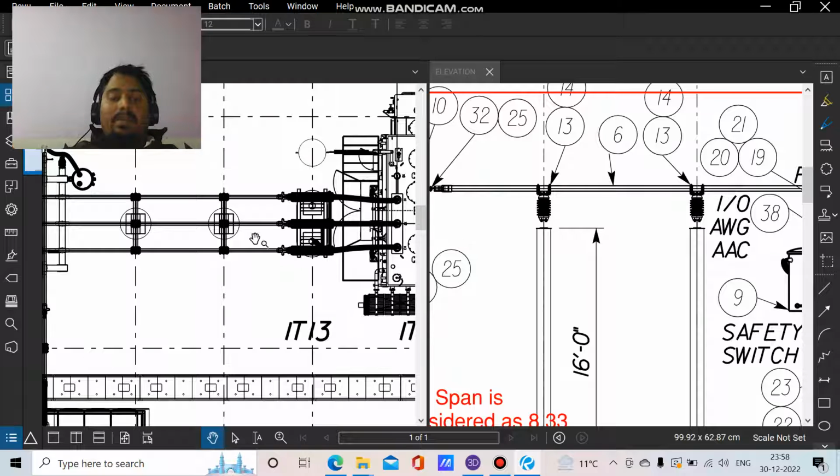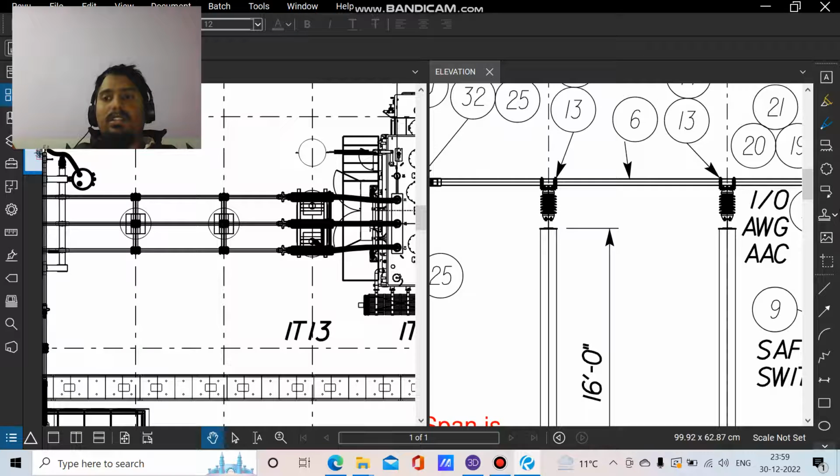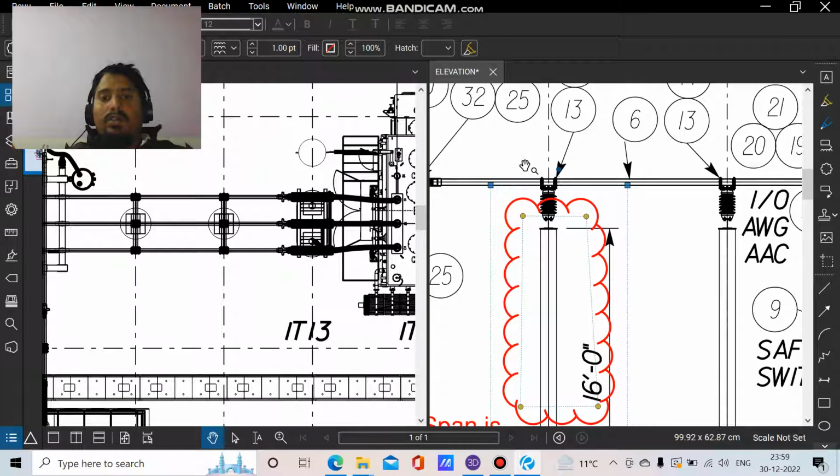So basically, apart from the conventional loads, there is a separate load which is the most critical, the short circuit force, combined with other forces, like we do the load combinations for our conventional loads. This short circuit force is also combined with the other conventional loads, and then we have the worst loading combinations. Based on those combinations we check the insulator and bus for strength, and after that we use the reactions derived from this rigid bus analysis to design these support structures. You can just mark it: these support structures are designed based on the reactions from the rigid bus analysis.